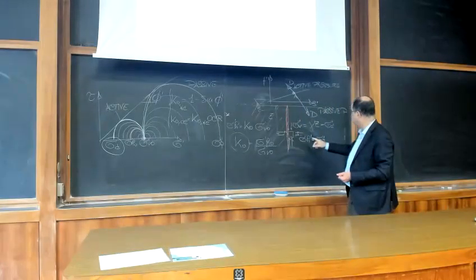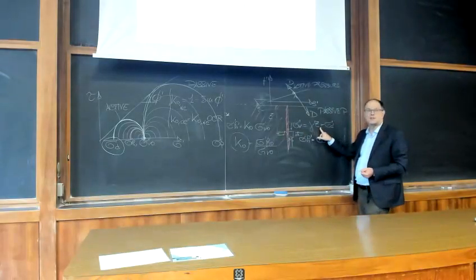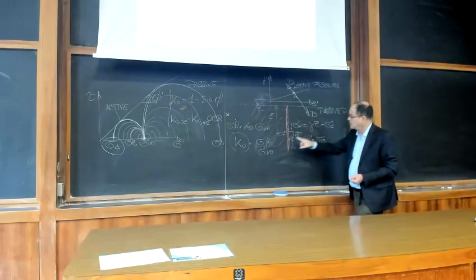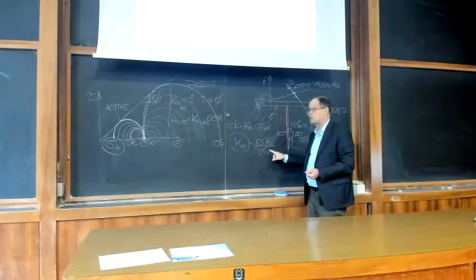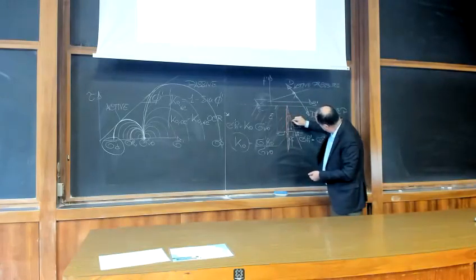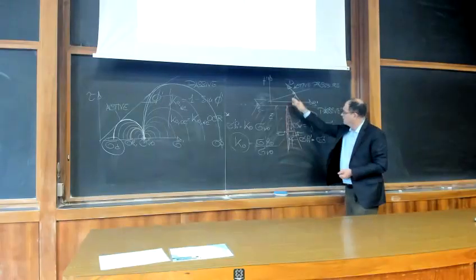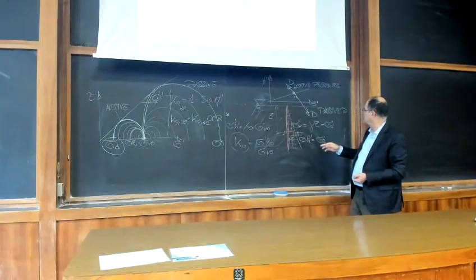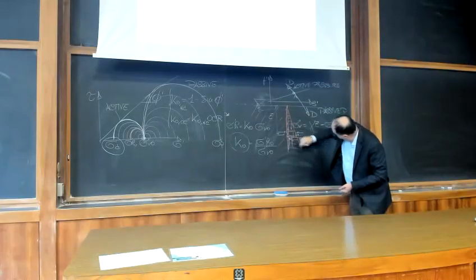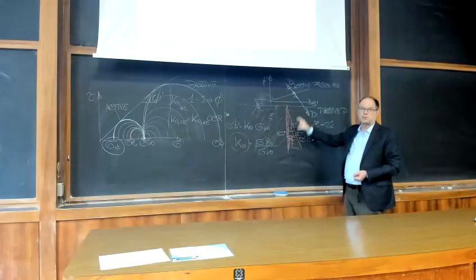Okay, and if you think about this, sigma h will increase linearly with z, because the vertical stress increases linearly with z. The horizontal stress is proportional, and so is also increasing. So you will have a plot of your horizontal stress which goes like that, and the resultant, as we mentioned before, of a triangle is applied at 1/3 from the bottom of your wall.